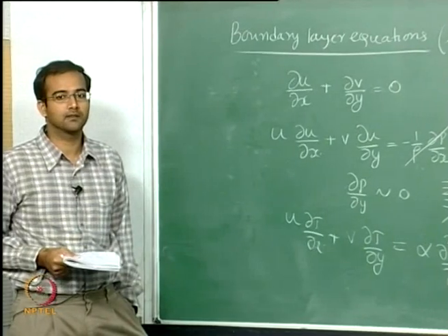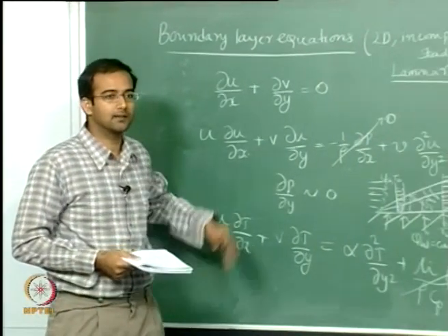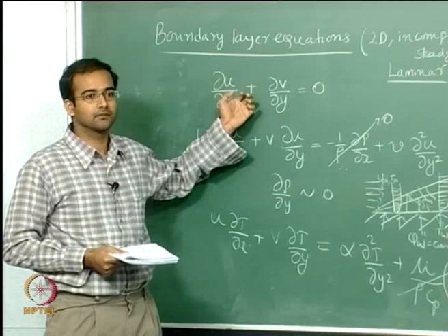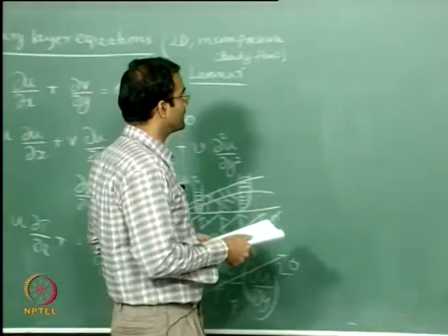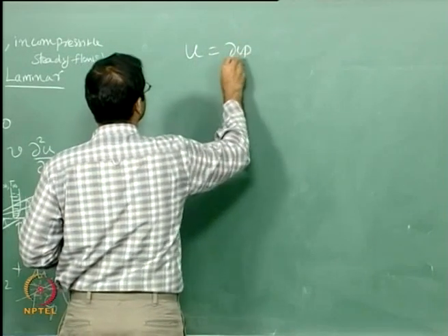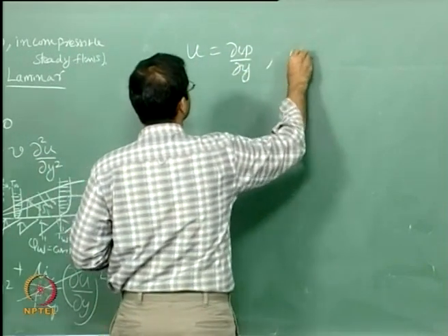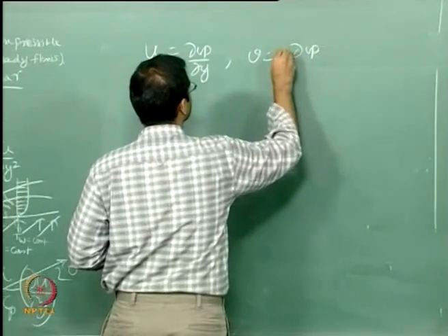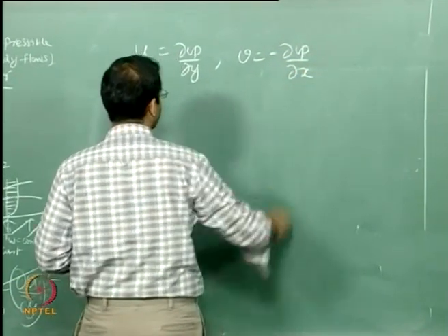Stream function. Okay, so the stream function naturally satisfies the continuity equation. Therefore I will introduce a stream function such that u is equal to dψ/dy and v is equal to minus dψ/dx.